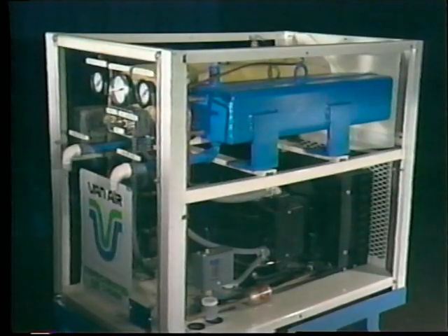To prevent frost from forming, refrigeration systems like the one we've just described are designed to operate at temperatures no lower than 32.4 degrees Fahrenheit. Here is an important point to remember. If you have a system where extremely dry air is required, chances are a refrigerant-type dryer like this will be used. This type of unit has relatively low initial and operating costs, so it's commonly used in industrial systems.